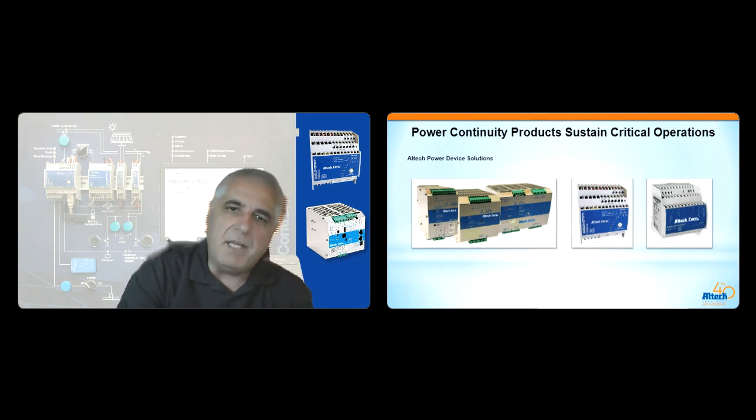Many times the management and monitoring features are critical. Evaluate the management and monitoring capabilities of the UPS, including remote management, monitoring software, and building communication interfaces based on your requirements.